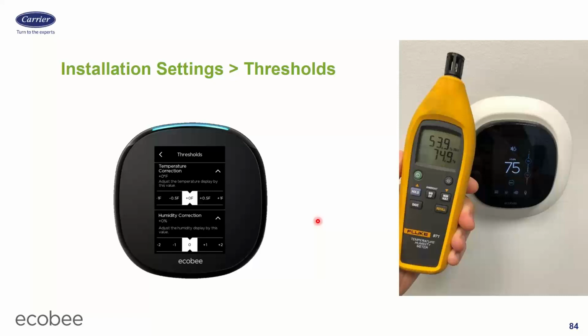If you go up to someone's outlets and you hold your hand over it in the winter and you feel a little bit of cold air, that same cold air is hitting the back of this thermostat. And Ecobee stats, more than other thermostats, are very susceptible to that cold air behind the wall issue. So if you have that issue, that's the first thing you want to check if the sensor's not reading what you think it should read. If you have that issue, you should seal that hole up with a can of expanding spray foam.